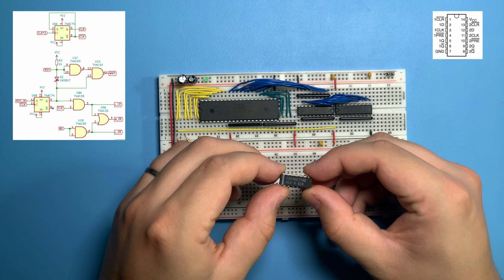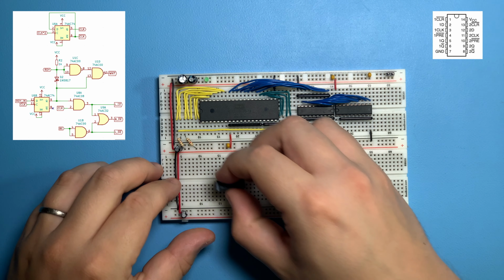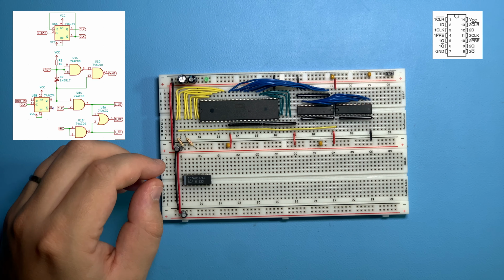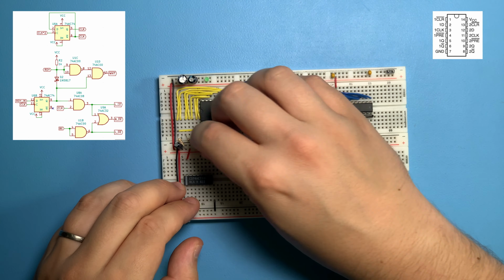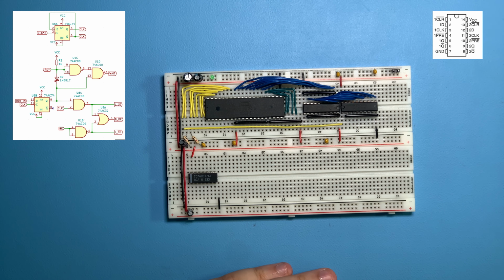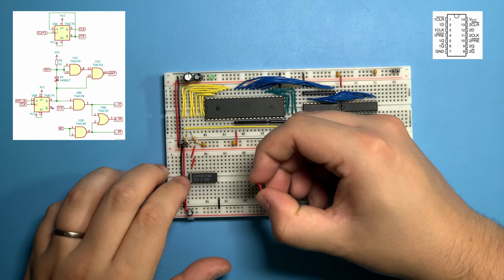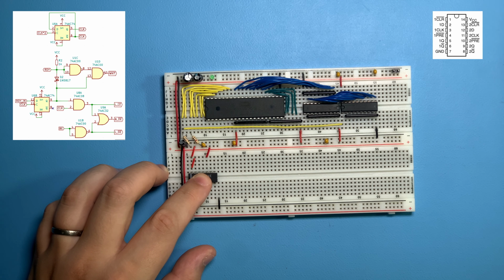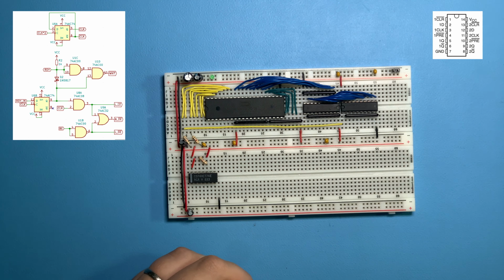So I have here a 74HCT74 dual D flip-flop. I'm going to put it here on the left. VCC and ground. And so the first circuit at the top here is going to be our clock multiplier. So I need to connect pin 13 and 10 to VCC. Pin 12 is going to be the ready input. And pin 11 is going to be the clock. And the clock we get from the frequency multiplier on pin 5.